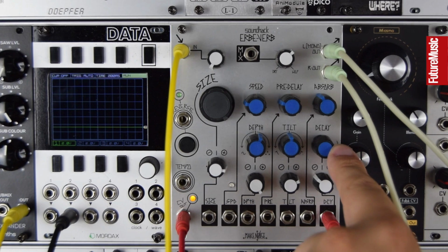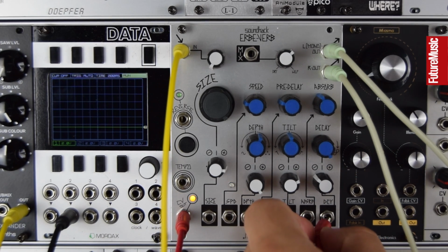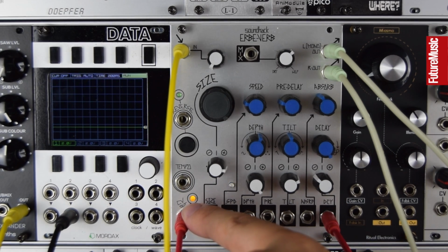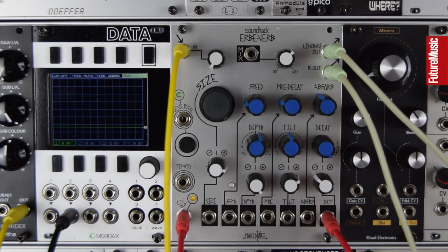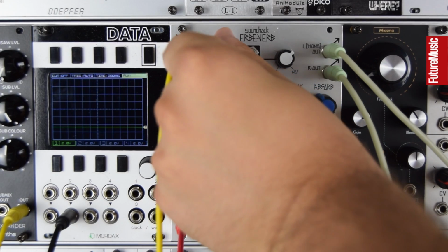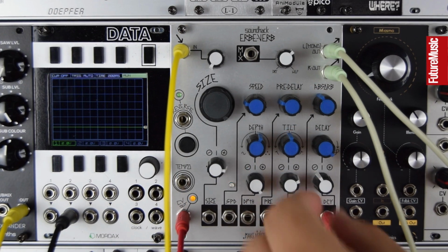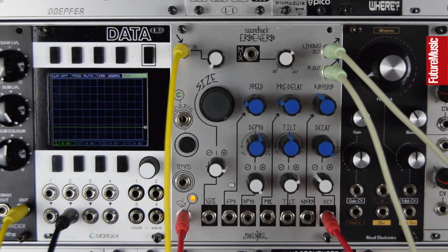So we can turn this up full, where normally this is going to run away with itself. As the output level increases, so does the CV out, and we're now inverting it to pull it back down. It will keep this sat at a kind of infinite level, and you can balance out the decay and the inverted CV in to do that.